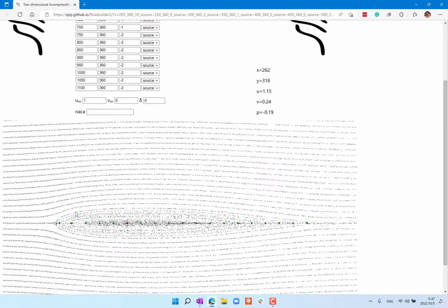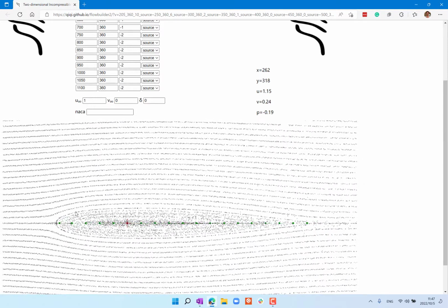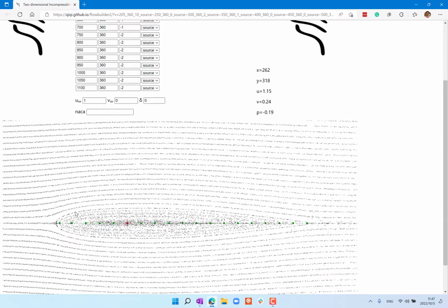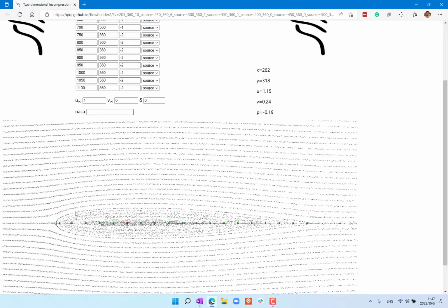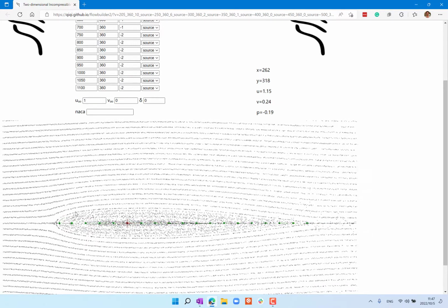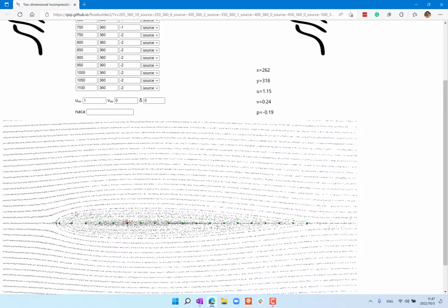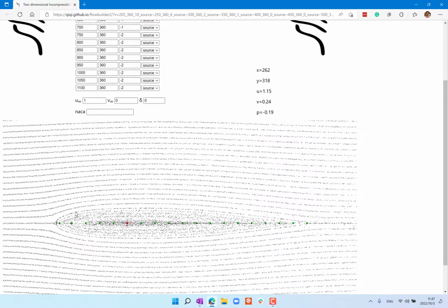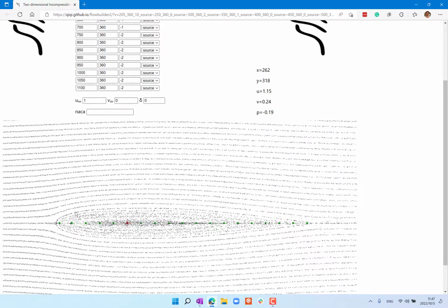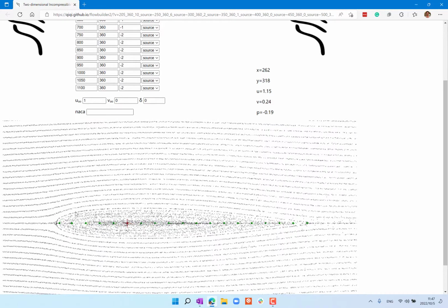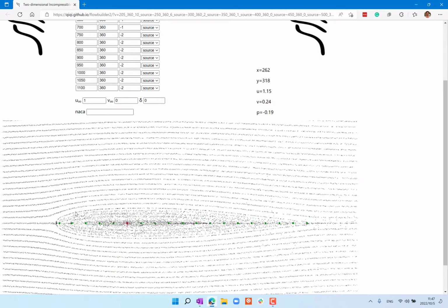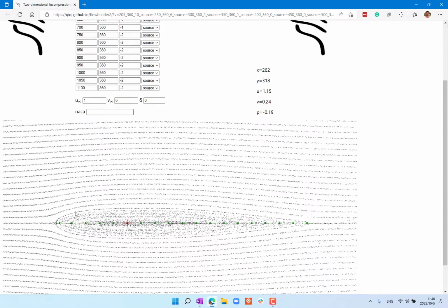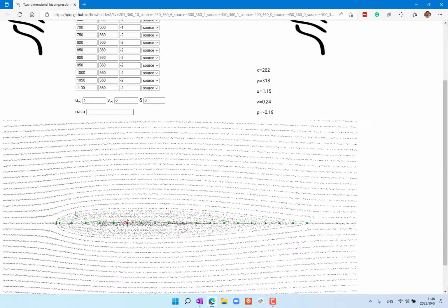Because if there is a high suction over here, I don't want to focus on this airfoil because it's symmetric, right? If you have a suction here, you have an equal and opposite suction over here, so it cancels out. But in general, when we move to non-symmetric flows very soon, in like 5 minutes, you are thinking about where the suction is, because that determines where exactly your lift acts, right? And as you change the angle of attack, is that peak suction moving downstream or upstream? That's very important.